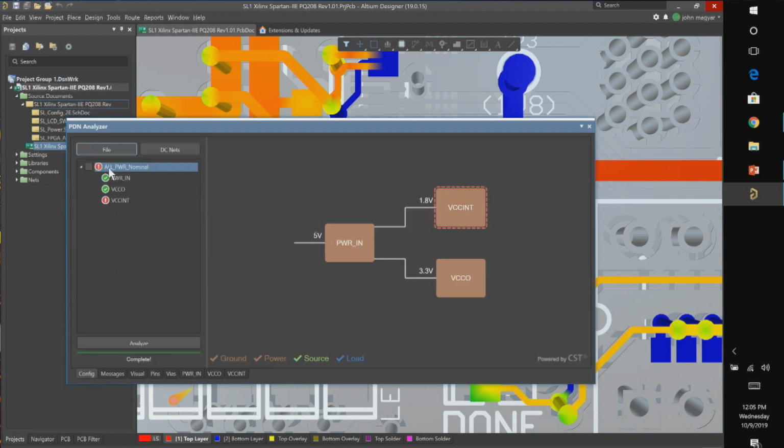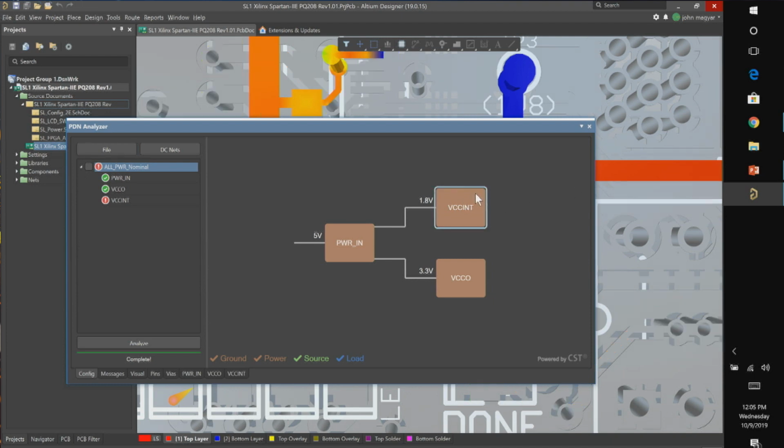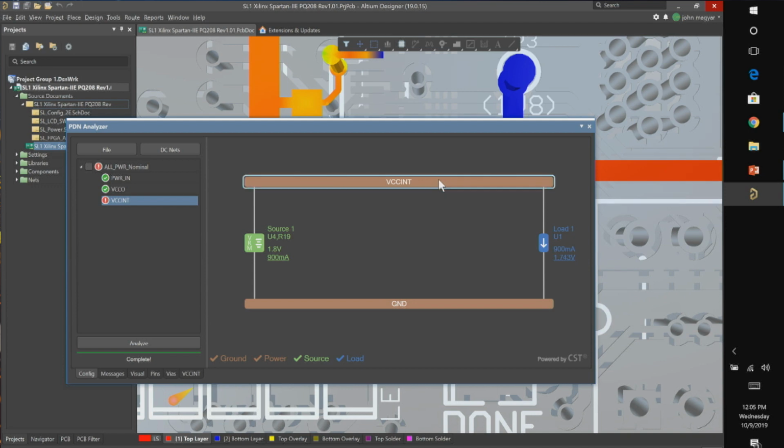So if I go back to the configuration, you'll see some red marks are highlighted. So when I was showing you that you could place constraint checks on the vias, it looks like that's what this is. If I click into this box, and you can hover over a message at some point or click it, yeah, it'll give me a little message indicating that a via was found where current measured was 900 milliamps and the limit was 850. So we exceeded that slightly. That's why we put checks in our design. And very, very visual indications have found that.